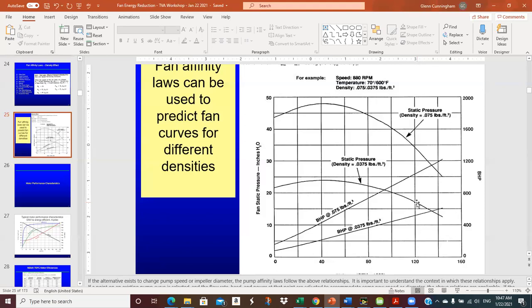So I would say it depends on how critical that fan is. If that VFD went down for a short period of time, how big of a problem is that for you? The other thing you could do is measure the pressure drop across the damper, or talk to the damper people, see what they would estimate it to be at your flow rate, and then use that simple little equation, or do it in one of the calculator tools and see how much having that out of there would save you a year.